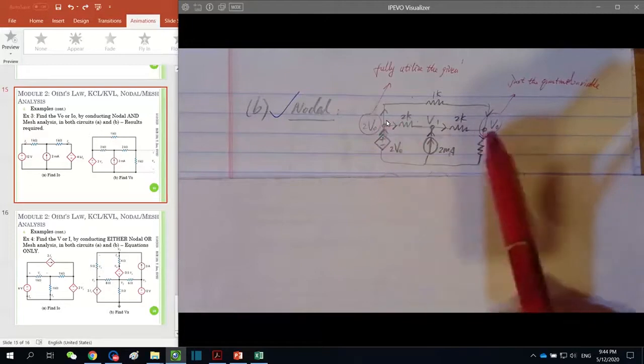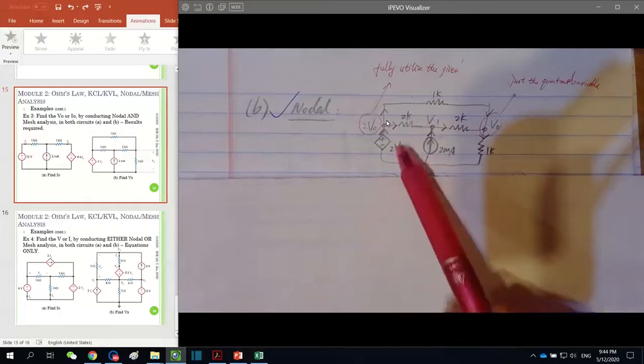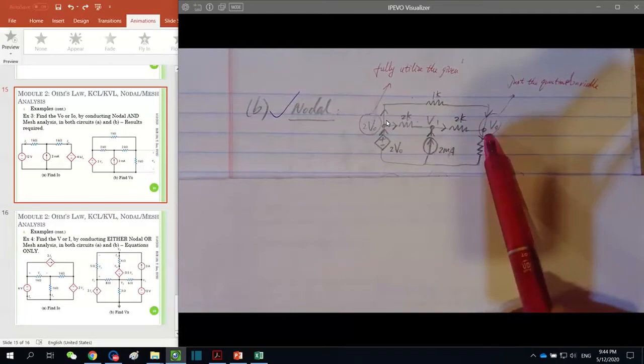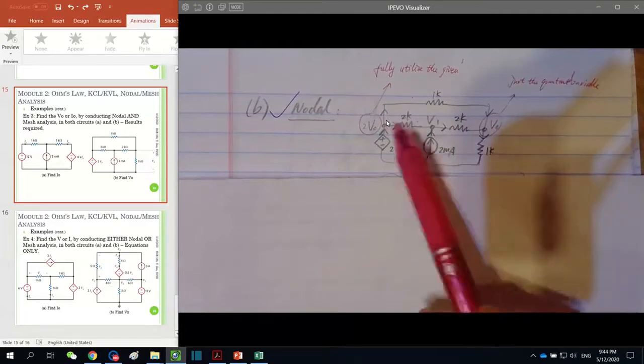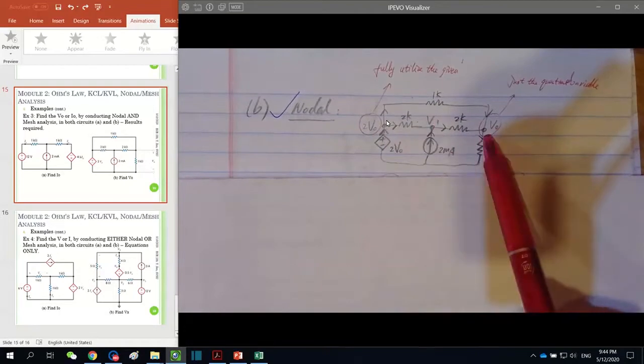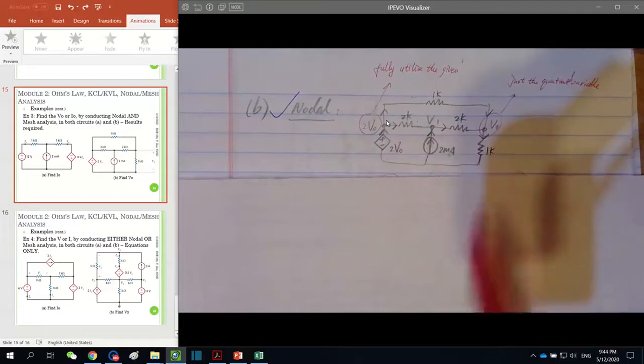By doing so, I'm reducing the number of unknowns in the equations. Because otherwise, here is V1, here is V2, here is V3, 3 unknowns. Now basically, we have 2 V naught here, V1 here, V naught here, so 2 unknowns. However, of course, if you assume V1, V2, V3 here, it is still doable, it won't affect you finding the results. And based on these assumptions, let's see the equations.